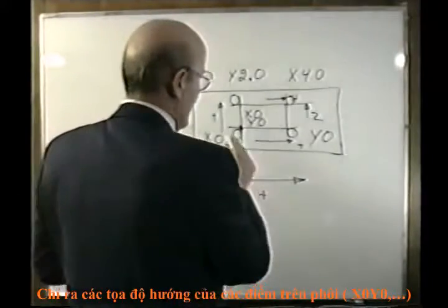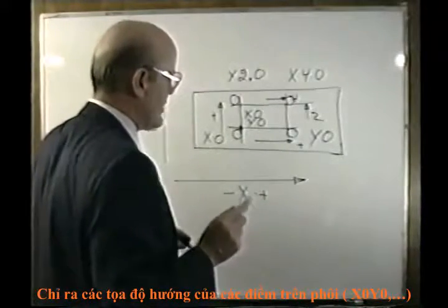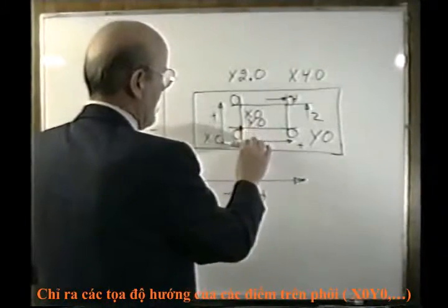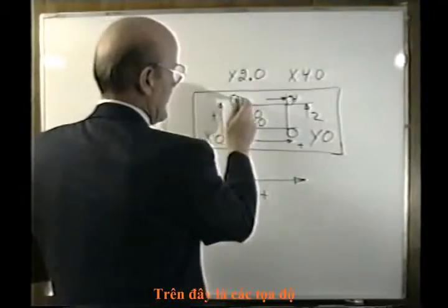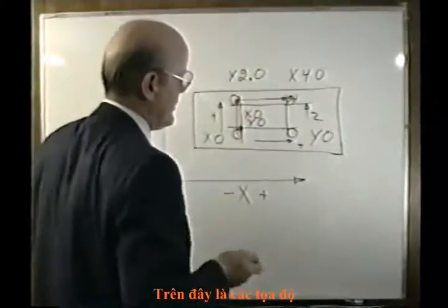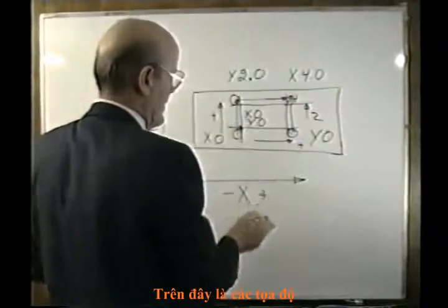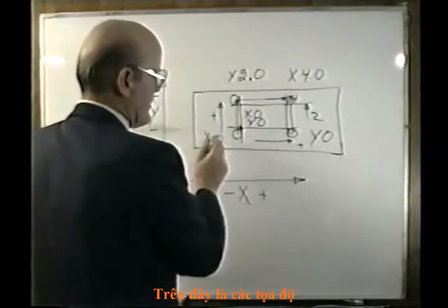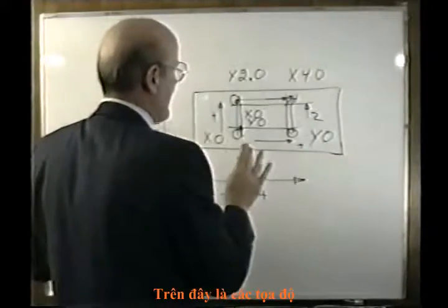So normally, if we have a square type of part, we pick the lower left-hand corner, because we can call that 0, 0 through coordinate system setting, and then we can actually program part dimensions. This point right here is y2.0. This point right here is x4.0, while it maintains the y2.0. This point down here is y0. And as I feed back in this direction, if I went back to here, it would be x0 again. Most likely I would go to some point past that point. Now that's on a flat part.